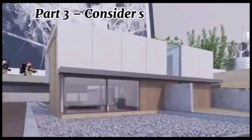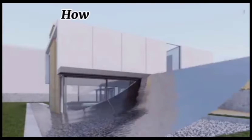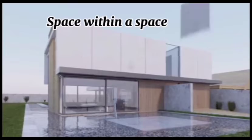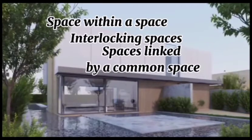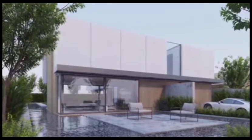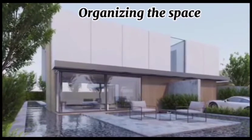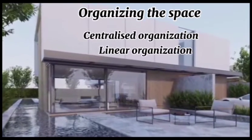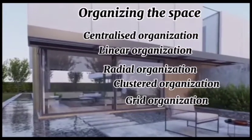Part 3. Consider spaces and spatial relationships. Spatial relationships include how spaces can be related to one another: space within space, interlocking spaces, spaces linked by a common space, and also adjacent spaces. You can also consider varying forms of spatial organization, some of which are more naturally suited to particular uses than others, including centralized organization, linear organization, radial organization, clustered organization, and grid organization.